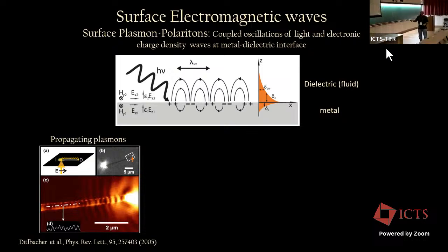So you can propagate such kind of signals. For example, you can illuminate, let's say, a silver nanowire, roughly about 100 to 200 nanometers in diameter, and extending over a few tens of microns, or at least multiple of 5 microns, where you will illuminate this particular wire at one end, and you will see the photons emerging out of the other end. This is all mediated through this wire. So you are able to now transport optical information through conduits whose dimensions are smaller than the wavelength of light.